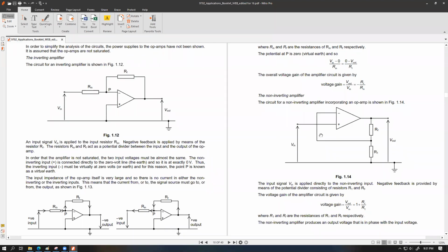And the feedback fraction is always connected to the minus. Here you can see, because the input was already fed to the inverting input, the feedback fraction was added to this, so we had a junction point over here. For this circuit, however, the feedback fraction itself is the V minus. So here is the output, here is the division of the feedback fraction. This is the feedback resistance, RF, and this is the R1. In this case, there is no Rin, because we don't need that.